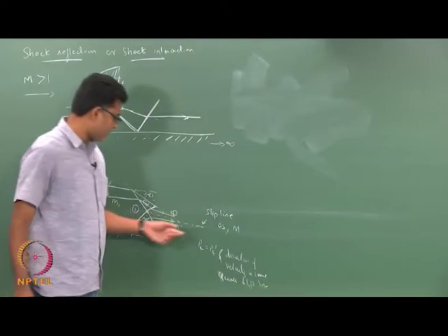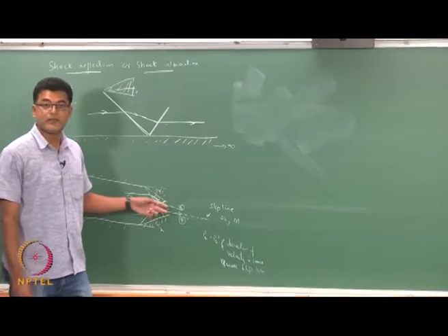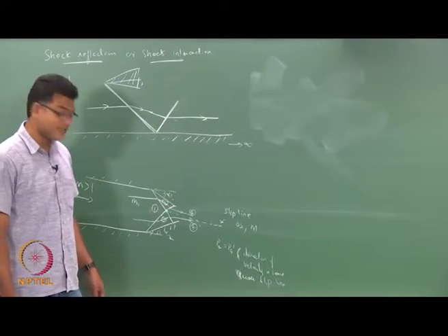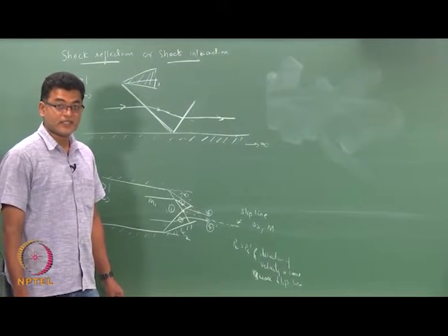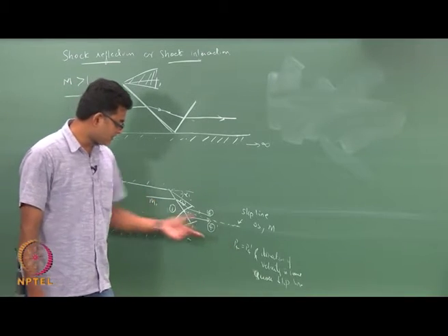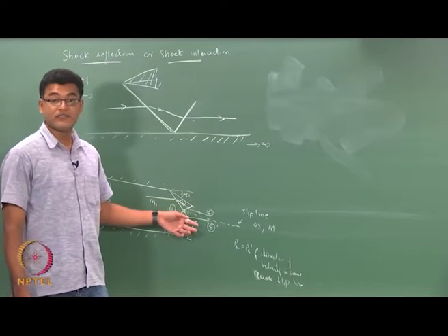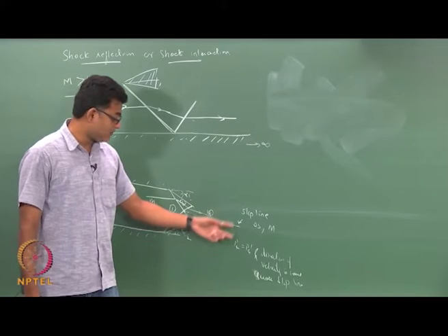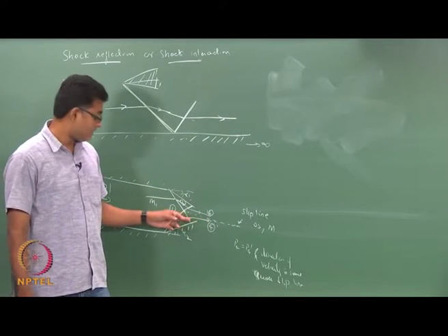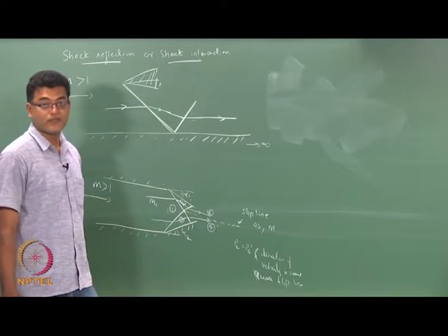All other properties can have a sudden jump, temperature can have a sudden jump, densities can have a sudden jump, everything can have a sudden jump. So, if you take a pressure contour of this, you are not going to visualize the slip line, whereas if you plot the Mach number contours, you will see a slip line according to this particular configuration.